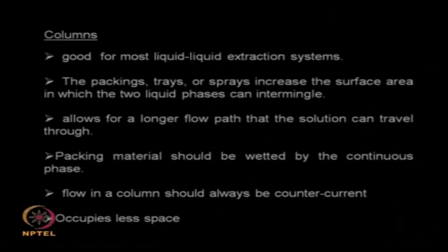Columns are very good, they occupy less space. I can have many stages, I can put in many separators inside the column in the form of a tray, and each portion is almost equivalent to an ideal stage. So, it is very good for liquid extraction.